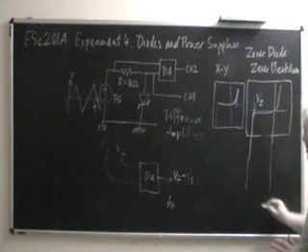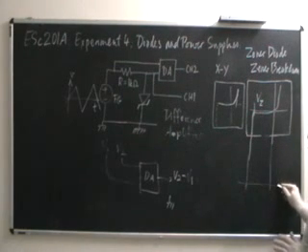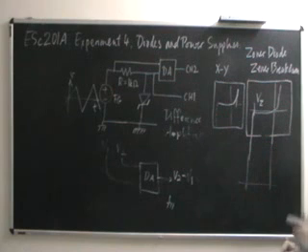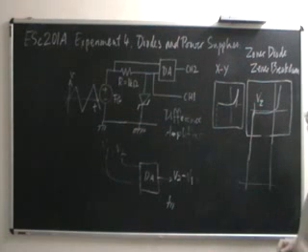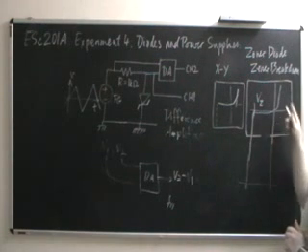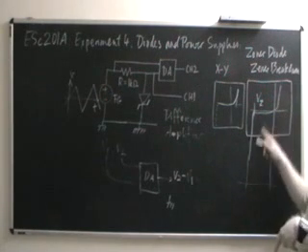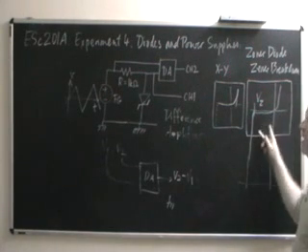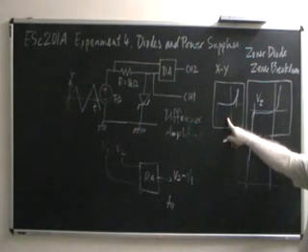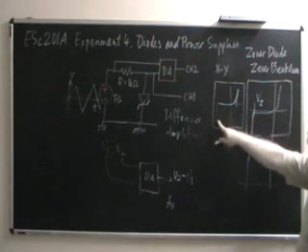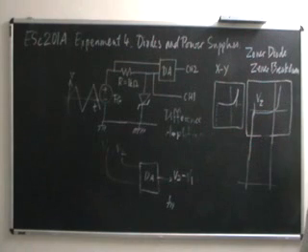This is the current axis after all, and there is a maximum current beyond which, if you drive this in a diode, it would just burn out. It would overheat and burn out. So we don't want to do that. We want to just look at the characteristic of the Zener and plot its characteristic as we have done. Compare this characteristic with the ordinary diode's characteristic without the breakdown part of the curve. So this much is part 1 of.